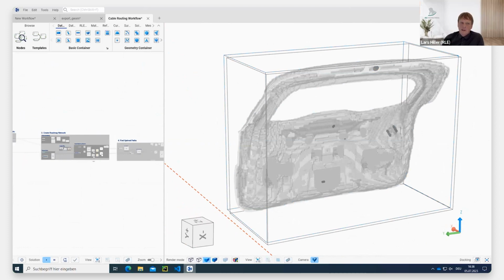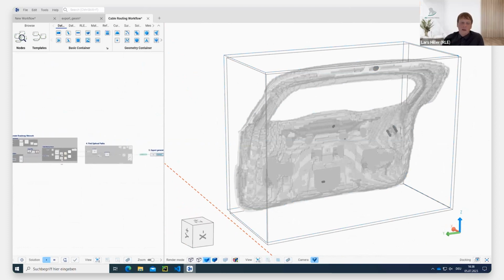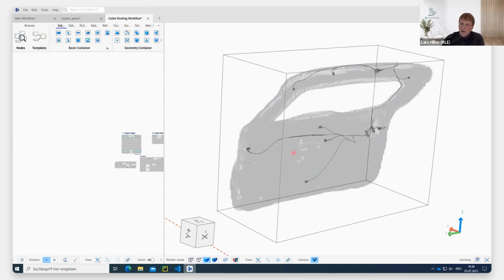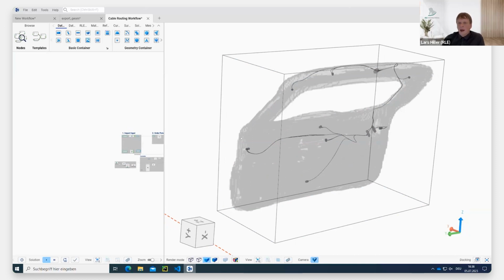Another step that is already available more or less in Synera is using AI optimization, if you want. So you need to define all the places where a hole could be, and the Synera workflow could use the ant colony optimization algorithm that is already available in Synera to go through all the possible positions of holes and find the best one. Another optimization approach, which is not yet implemented, so that would not be ready, but it is available, and we could just do that.